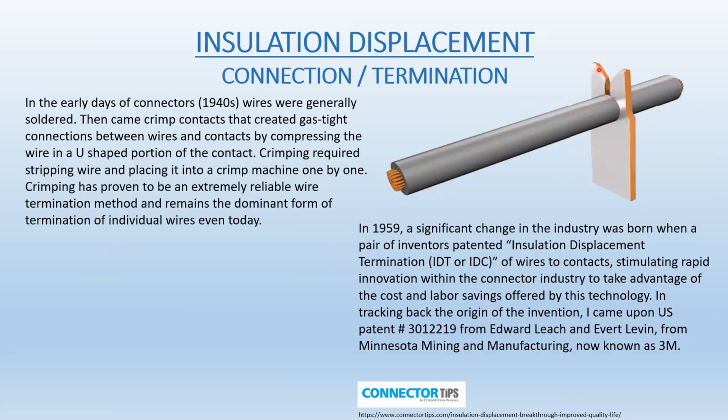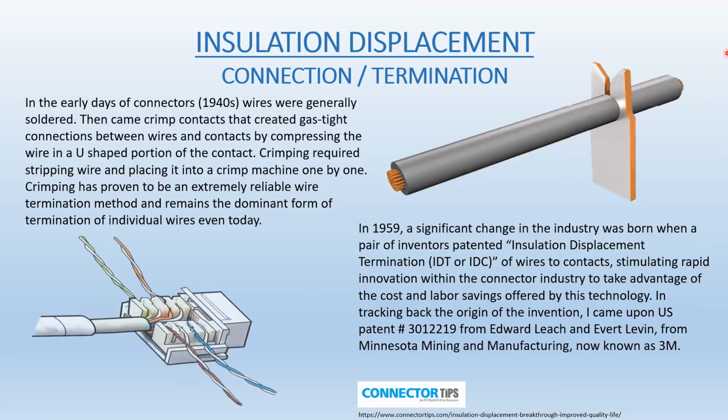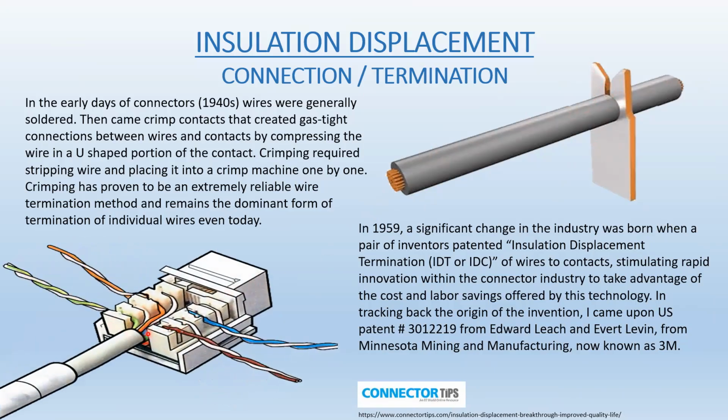Here's the connector. The wire is being pushed into that connector. That connector bites into the insulation, makes contact with the copper wiring inside. Thus, it's called insulation displacement connection, IDC. And this is how things are being done. We're doing the lab, we're doing those connections. This is one example of IDC that we're doing right now.